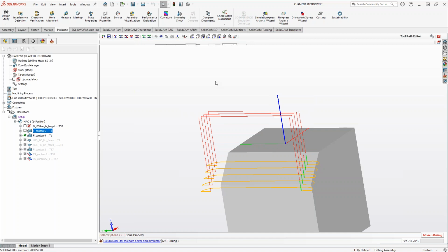Because this is the kind of thing that I'm going to hold in my toolbox waiting to be used. I'm not really thinking of when I'm going to use it now, but I'm for sure going to use this as an option if there's ever any time where a toolpath is just doing that one little weird move. Let's say it's a translated surface and our 3D toolpaths are just not reading it well enough because of the fact that it's been translated. This is a good way to remove any kind of the noise you get with the data points on a translated surface. You can easily trim out any weird, erroneous movements using this, if you can really zoom in and grab those points.